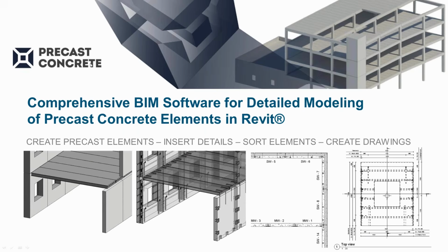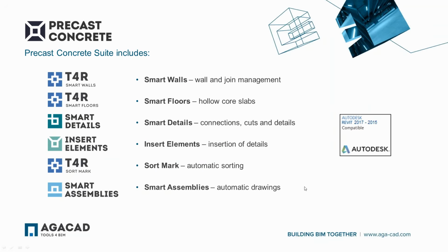We'll talk about precast concrete, and it has tools inside for precast modeling, for the insert of details, connections, cuts, and so on, and sorting of elements and creating drawings. So these tools are inside the precast concrete: smart walls, smart floors, smart details, sort mark, and smart assemblies. Most of the functionality of insert elements is now implemented in smart details.